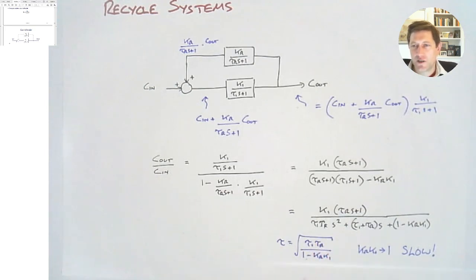So with a recycle, with this condition, if the steady state gains of your process in the recycle start approaching 1, the whole process can become incredibly slow to respond to a perturbation. So that's another point to watch out for.